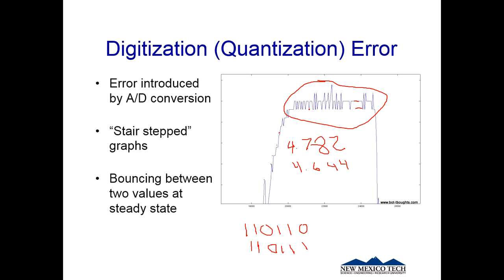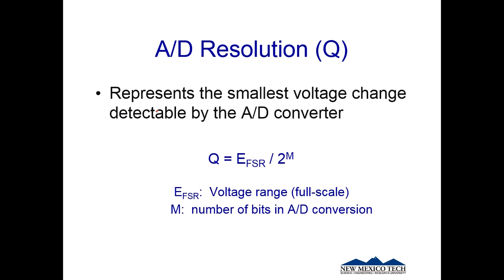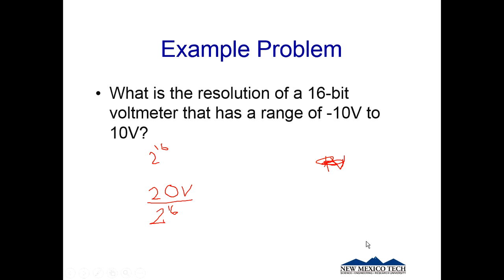And so just as a review, basically digitization is going to be a big deal. You need to make sure when you're designing an instrumentation system that your resolution is small enough to capture the changes you expect to see. So that's what I've got.